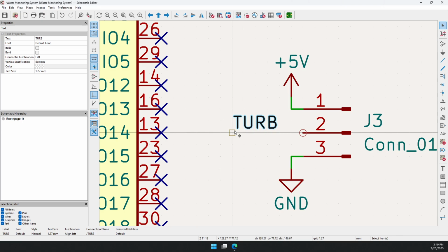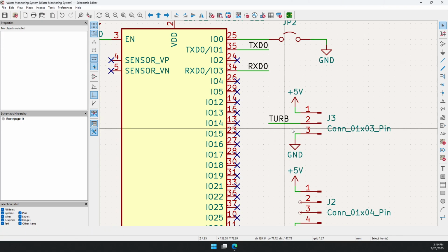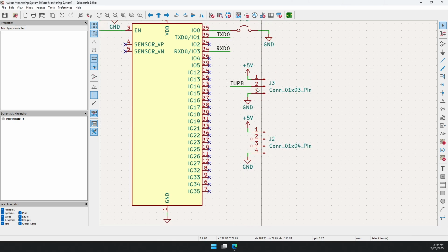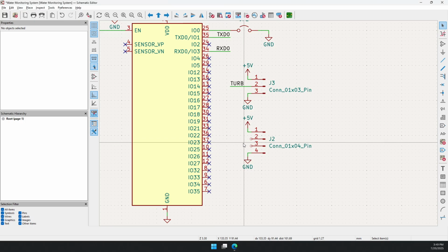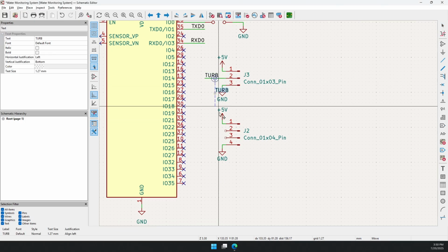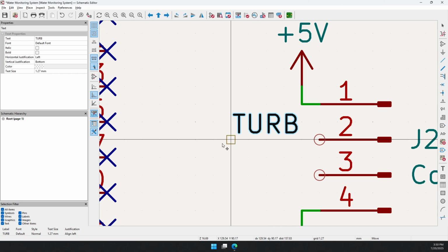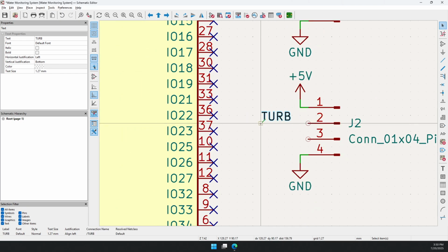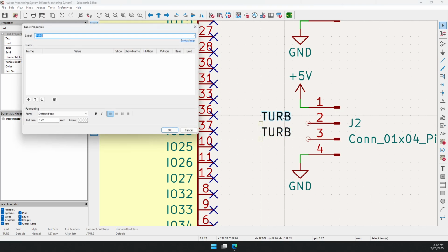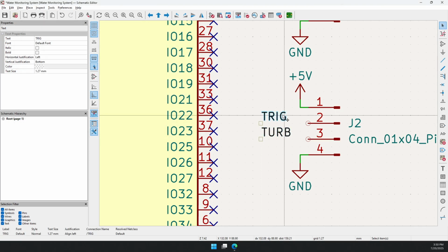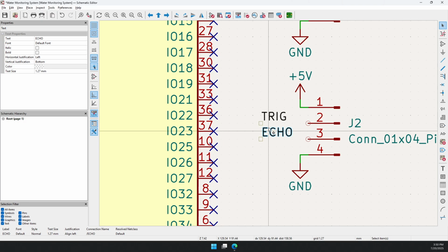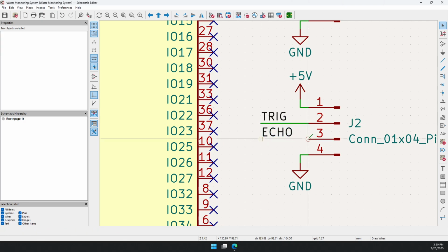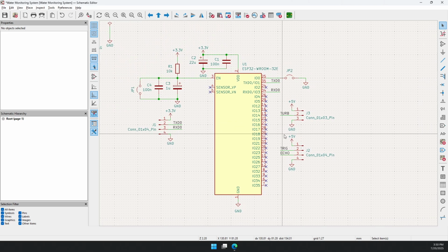So I'll call this tab and connect this here. Okay, so I just have to worry about this later. What was the pinout for the ultrasonic again? 5 volts, trig, echo, ground. Okay, trig, echo, ground. Trig and echo. Hook those up to.